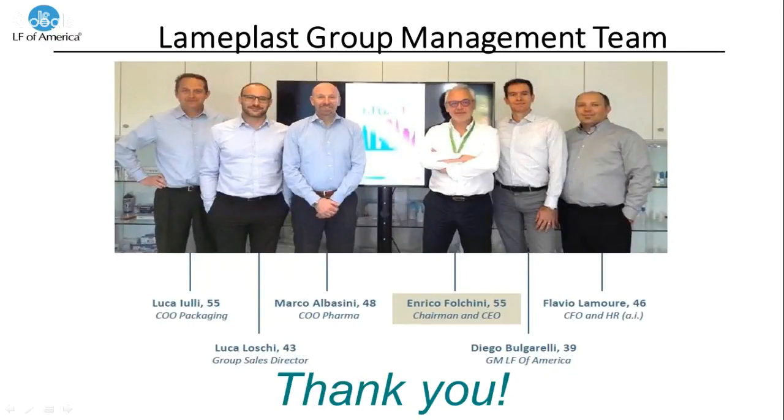Great. So another one regarding the EVOH barrier. Is the barrier created in the molding process, or is it created past filling? The barrier is created in the molding process. One amazing thing about the molding process of the EVOH is that if it's injection molding, we're able to inject, and if it's blow molding, we're able to blow different layers of plastic during the molding process. So the layers are separate during the molding. However, of course, when the packaging cools down, they are invisible to the human eye, and they are all in one. Basically, you see only one wall.